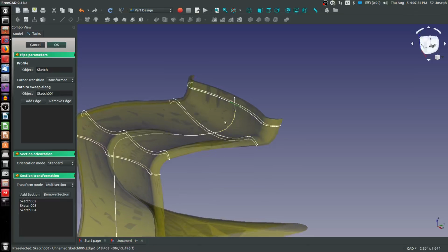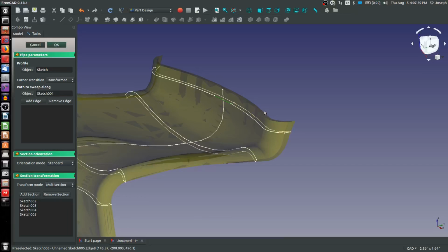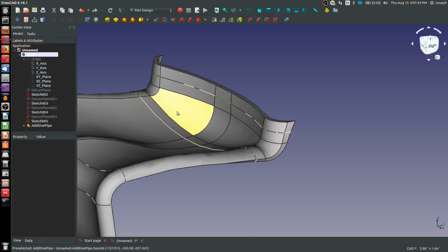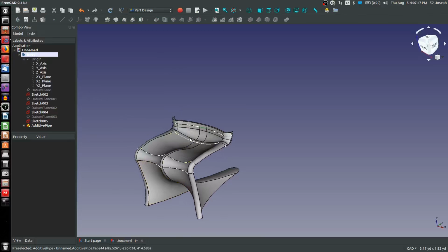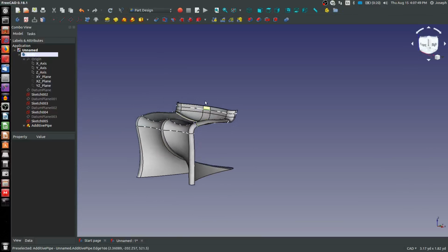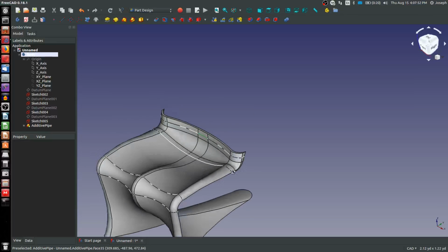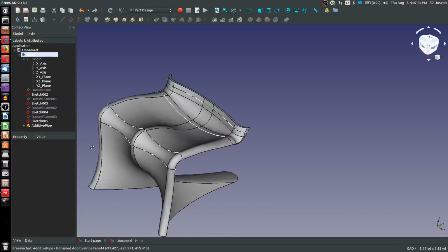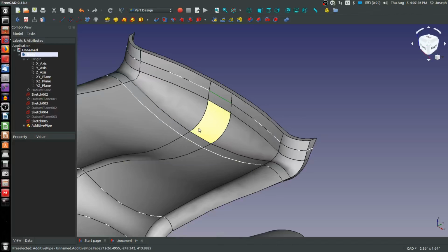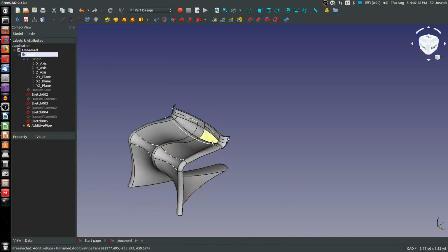And so running the path through multiple lines instead of a single one should allow this to end completely on a flat plane. Let's test that, because if I just end it on a curve, then it shouldn't give us very good properties when we try to add another sweep. So again, if I were to try to sweep out this entire back, it will affect this front face.